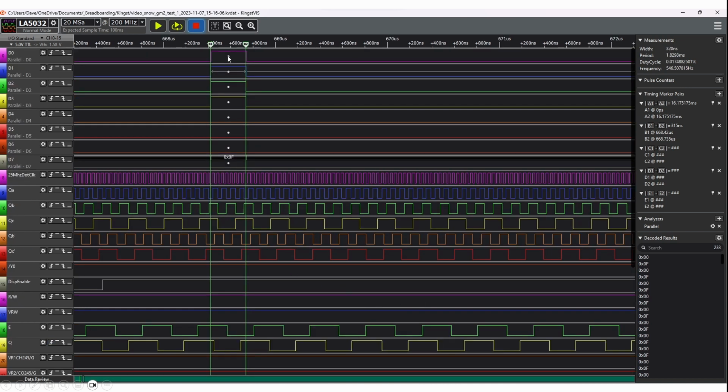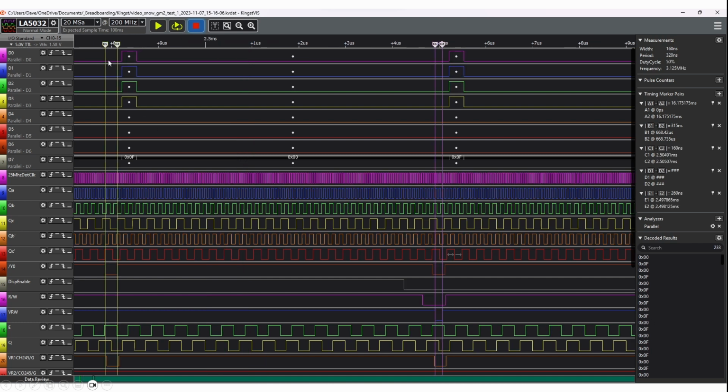And then this was the line at the very beginning of the screen. So we can see here that we've got a period of 320 nanoseconds, which is one character wide, 8 bits wide, has got a white line there. And then further along, what we can see here is where we're getting the interference.